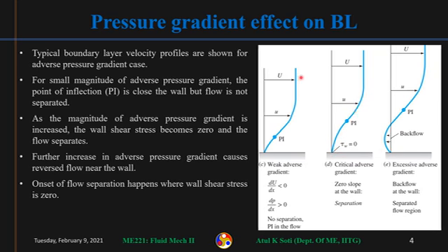So what is happening is, as you keep on increasing velocity, the adverse pressure gradient, this slope of the velocity profile near the wall, or you can say tau wall, both are related, right? Del u by del y will keep on decreasing. So this is y, this is the y direction and this is u. Slope is this thing, right?